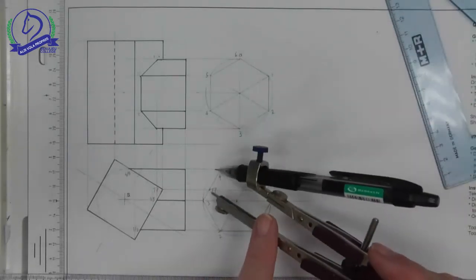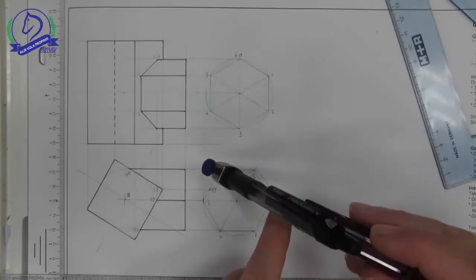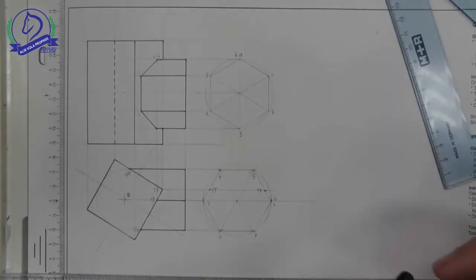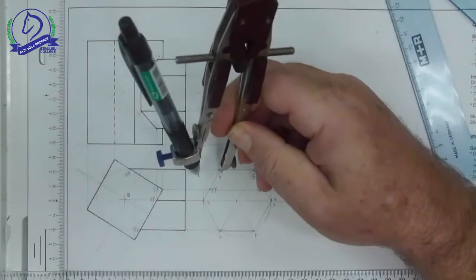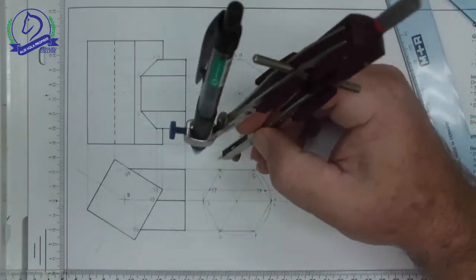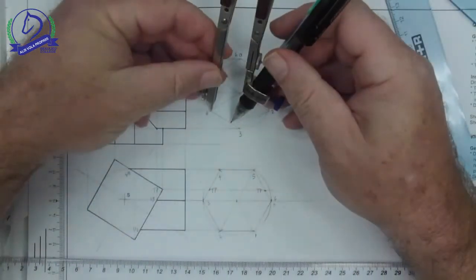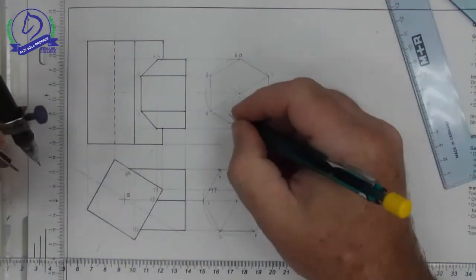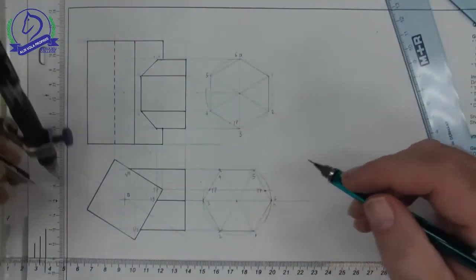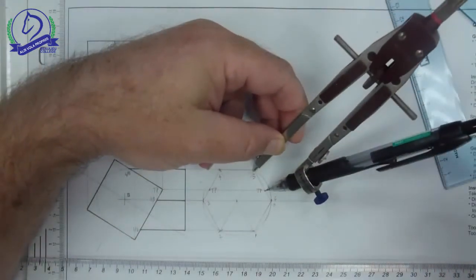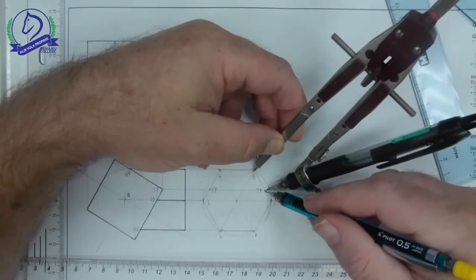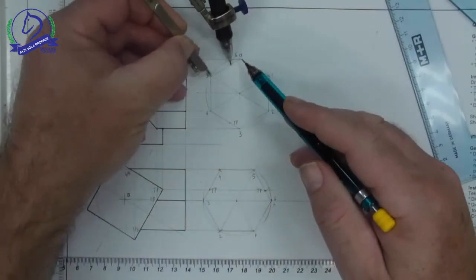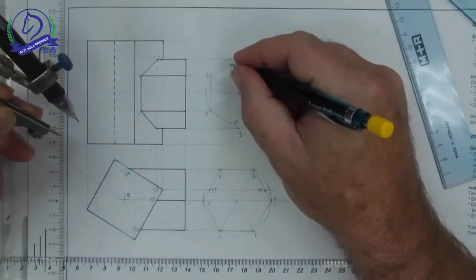That distance would be the same as the turning point to 4, and conversely if we rotate it from 4 to the turning point. This turning point was on the line going from 4 to 3. Here's the line of 4 going to 3. So where I measured was from 4, so I put my compass at 4 and mark towards 3. That gives us our turning point. The other side was 5 going to 6 or 0 to get the turning point. Do the same thing in my auxiliary view here: 5 going towards 0, mark that off, and there is my turning point over here.